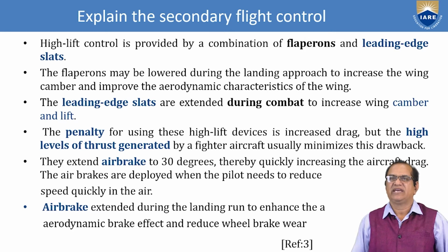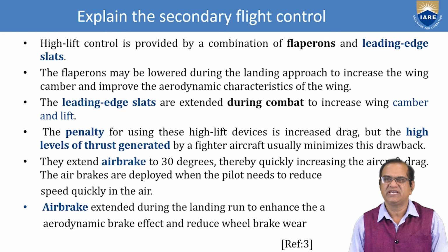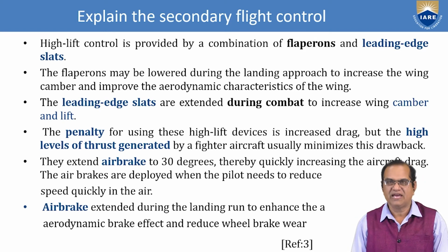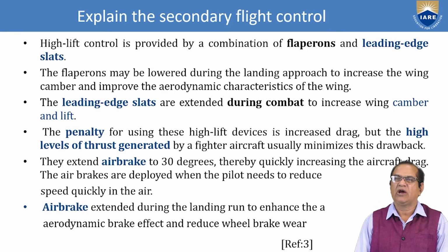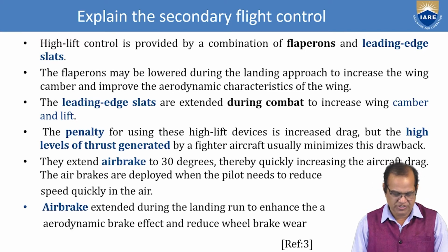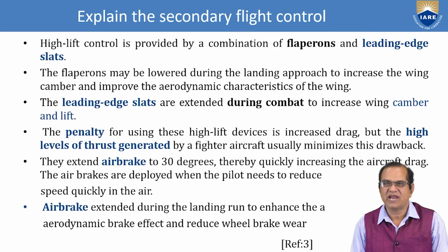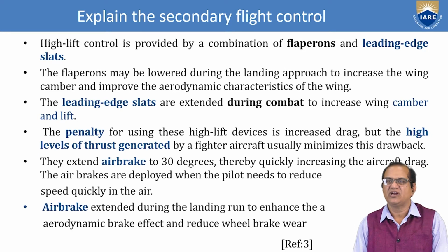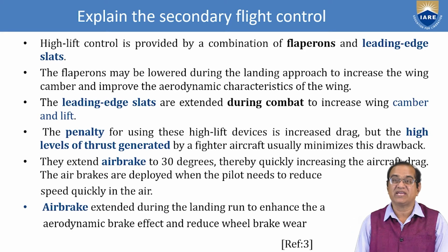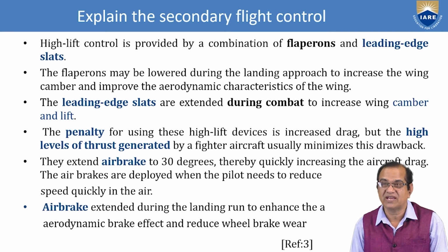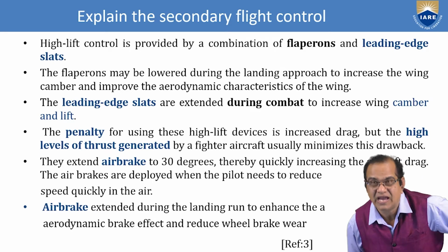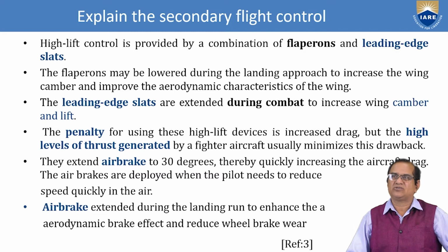They extend the air brake to 30 degrees, thereby quickly increasing the aircraft drag. The air brakes are deployed when the pilot needs to reduce speed quickly. Air brakes are extended during the landing run to enhance the aerodynamic brake effect and reduce wheel brake wear. So this I am going to discuss slowly.